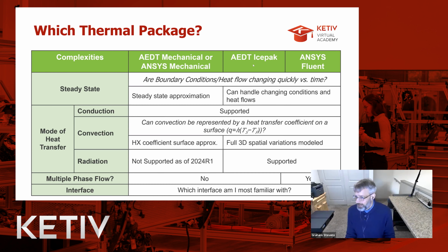So between IcePack and Fluent, typically where IcePack can't handle it is if you have some sort of multi-phase flow, then you would need to go to Fluent, but for the most part, you would stay with IcePack. You might also have different familiarity with these different interfaces. So AEDT is a different interface from Ansys Mechanical, which is a different interface from Ansys Fluent.